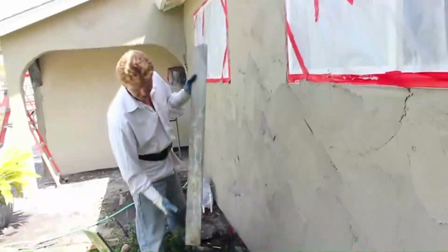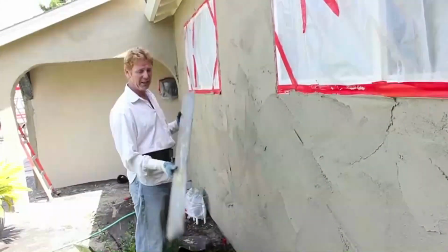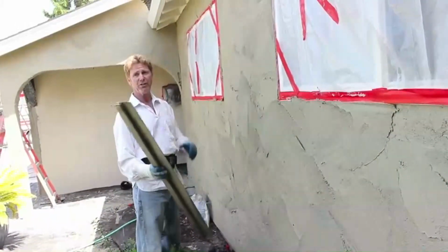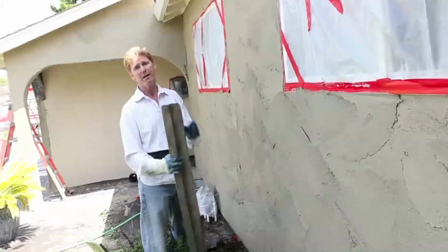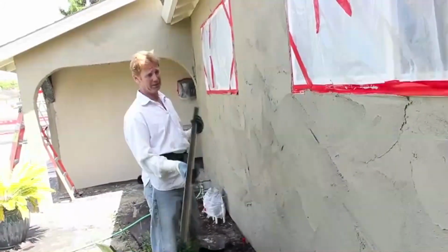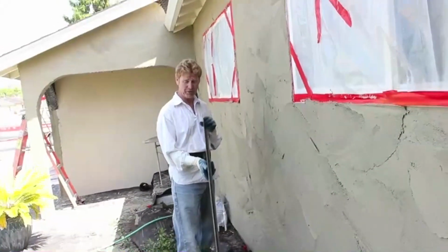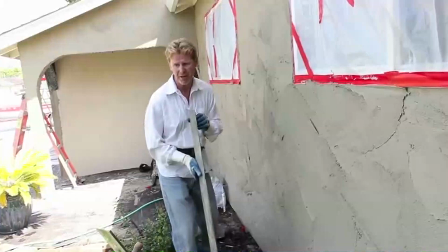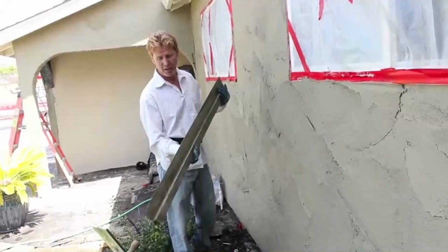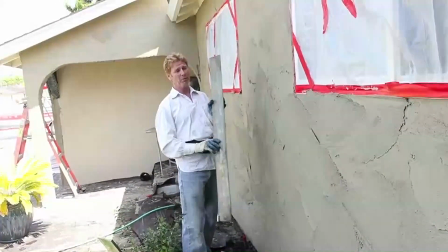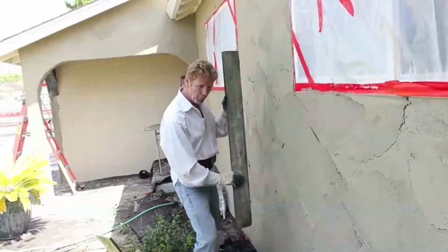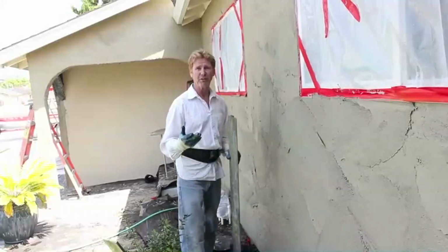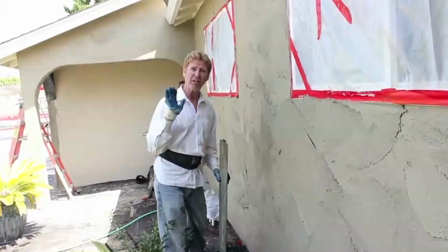All right, for my buddy in Australia, the land down under, they use a T-square. It's just like this, except it has one flat edge. It looks just like a T. Here in the States, California, we're familiar with this. This is a straight edge, a feather edge, a rod. And when I worked union, it would be one guy on one level, me on the other level, and we'd take a 10 or 30 foot rod and we'd rod walls, banks, specifically where they're going to put imitation tile on.